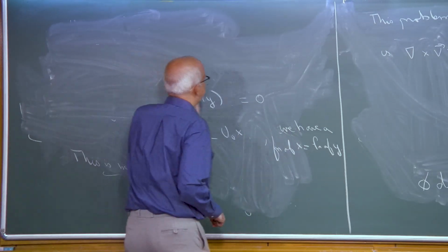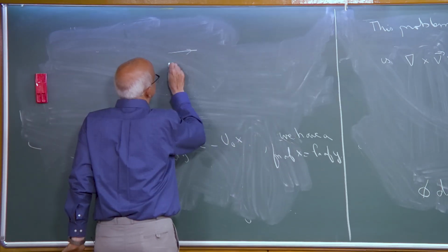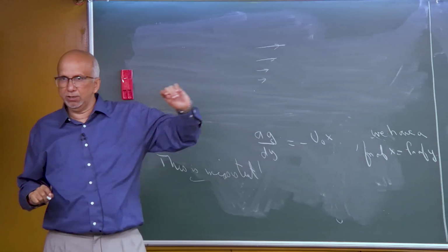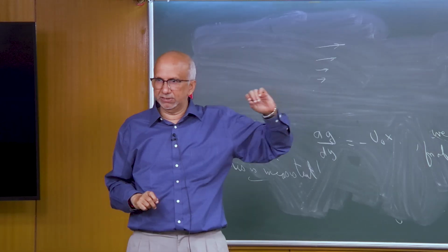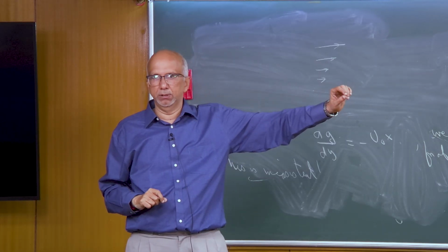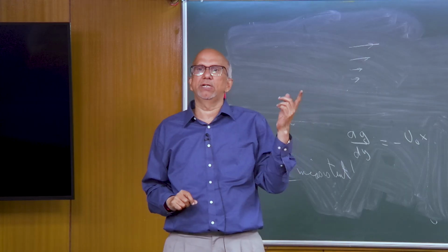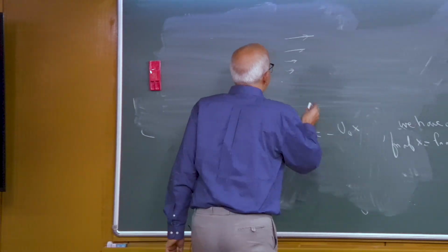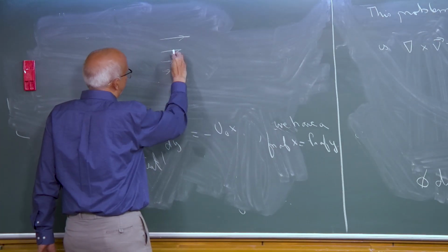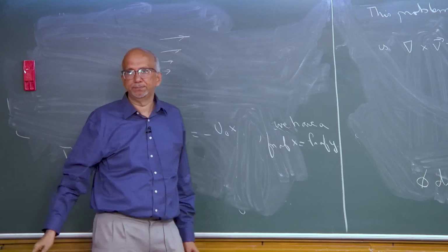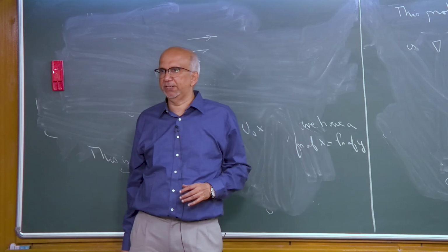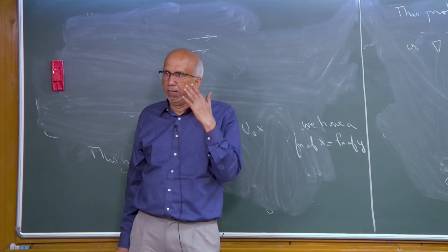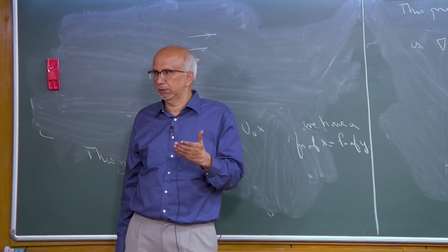the streamlines are all pointing in the x direction. So, it looks like the velocity field is all linear, in the sense all the particles are going in the same direction. So, where is the question of rotation? The particles themselves are not rotating, they are all moving, but if I were to put some small needle here, this guy will go faster, this guy will go slower, and that needle is going to rotate because of the difference in the velocities. So, by looking at the flow field, you cannot conclude whether the flow field is irrotational or not. That is the point I am trying to make.